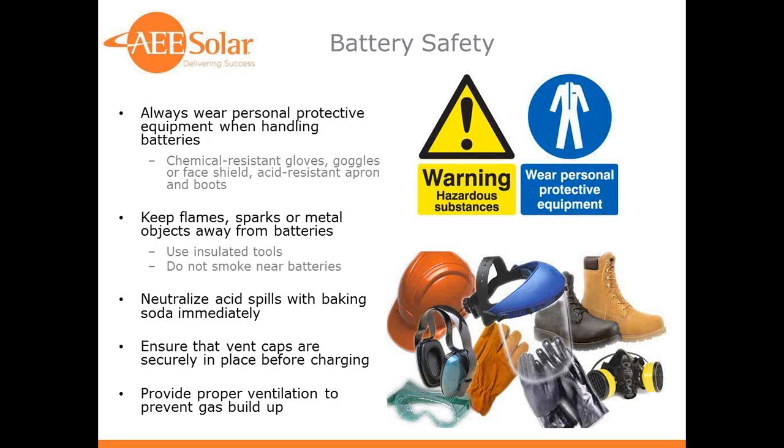And of course, proper ventilation is very important to prevent gas buildup. The primary gas we're concerned with is hydrogen gas, which is very flammable in the presence of oxygen. Obviously, it produces water when it burns. It does take about a 3 or 4% concentration of hydrogen to be explosive, but we don't want to get anywhere near that point. However, hydrogen gas is also very light, so it's very easy to dissipate through proper venting and vent at the topmost part of a battery enclosure or a battery room.